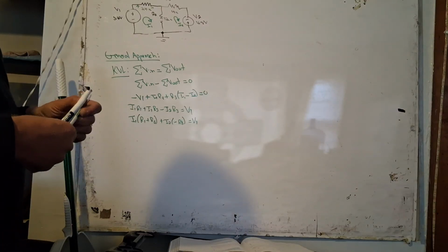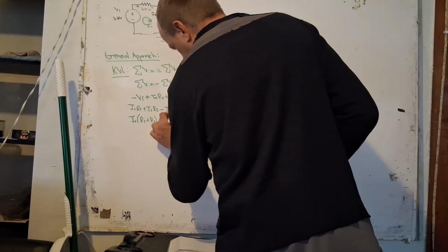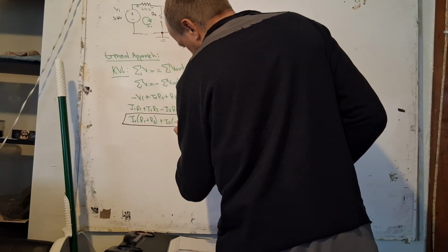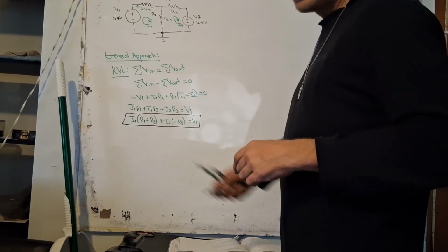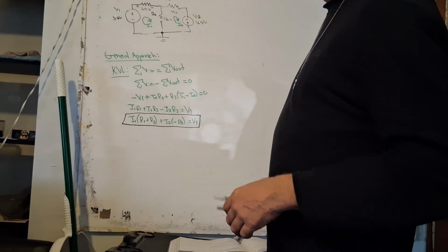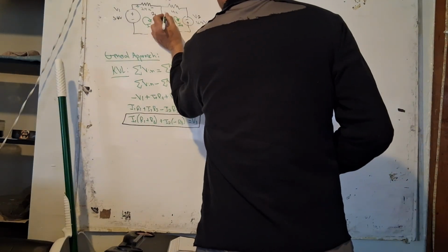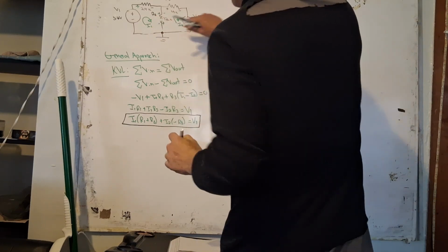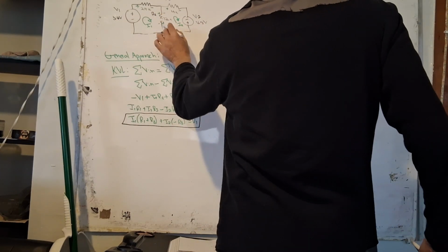This right here is half the answer to the problem when they ask you to find the equations, the mesh equations. I could do the same thing for this side. Start here, go in this direction, positive here, negative here, positive here, negative here. Notice that I put positive up here on this side because that's in this loop. This one over here is down in this loop.